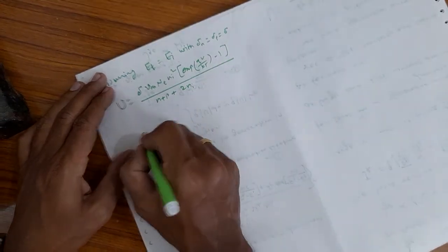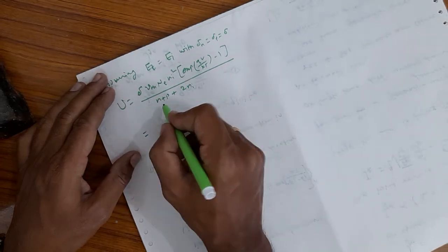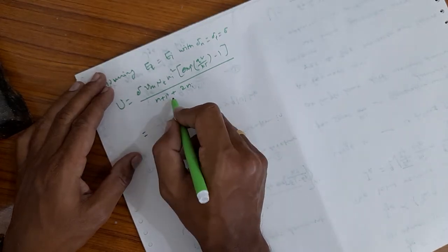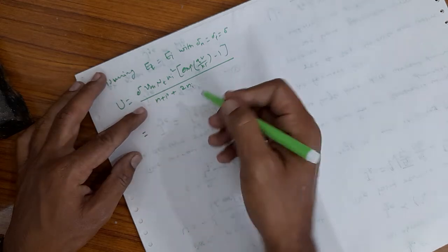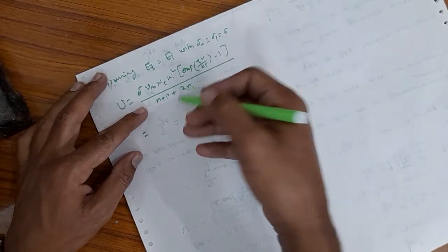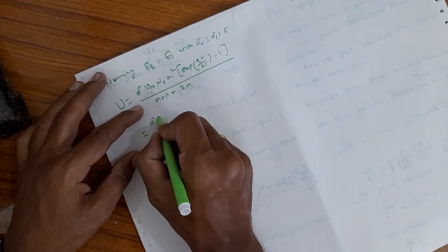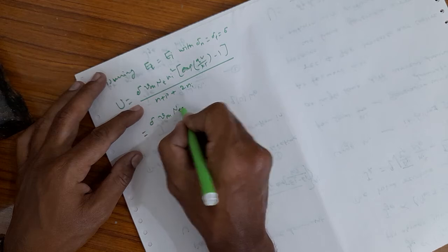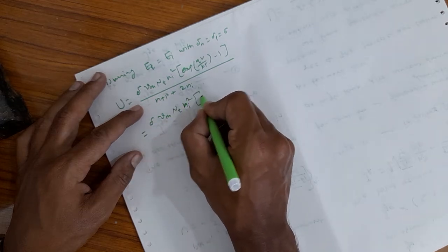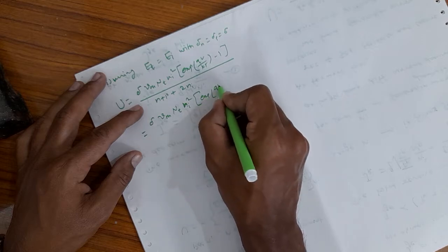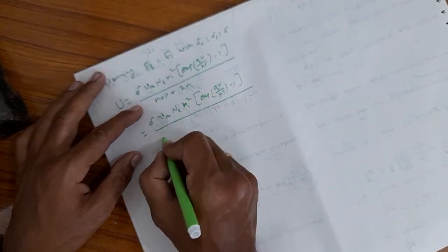So this is given in terms of the n and p values. We can substitute the n and p values, that is n equal to Ni into exponential of EFn minus Ei upon kT and so on. So we will substitute those values, and what we will get is sigma phi th Nt Ni square exponential of qV by kT minus 1 upon Ni.